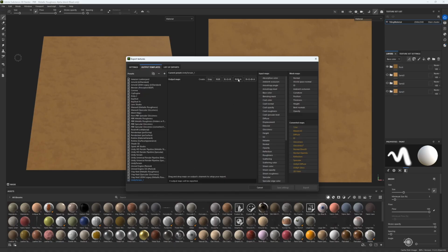And we want to add an RGB plus A. This one we're going to call $texture set. This will append the name of the texture set at the start of the texture. Then we'll do an underscore diffuse. So that is our color. And then underscore smooth. And the Unity terrain uses the alpha value of the color texture as the smooth or inverse roughness value. Now we're going to click on RGB and call this one $texture set underscore normal. So this will be for our normal map.